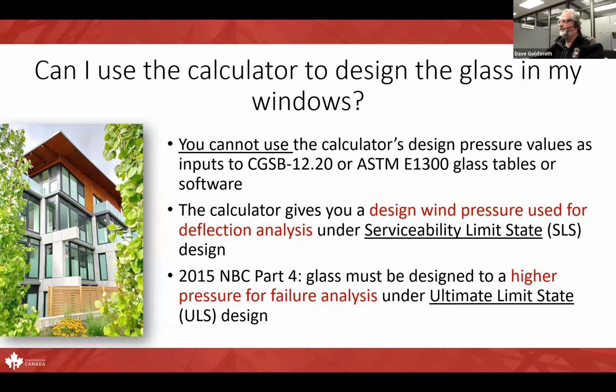So where I start to get concerned, if I see greater than 1 kPa design pressure, you're getting into the area where your standard glass thickness schedule may not suffice at the higher permitted areas for 4 mil and 5 mil and so forth.